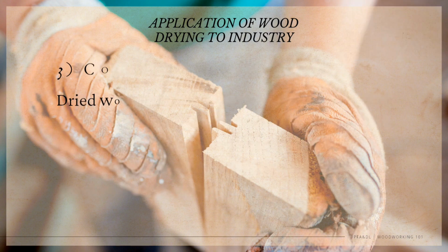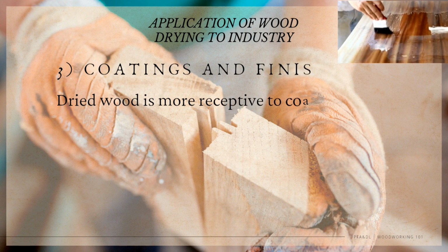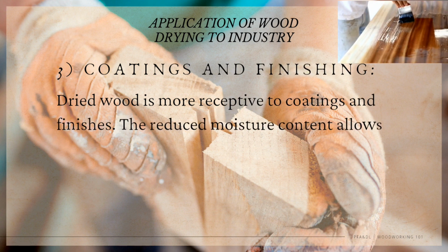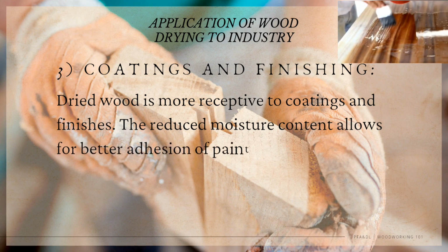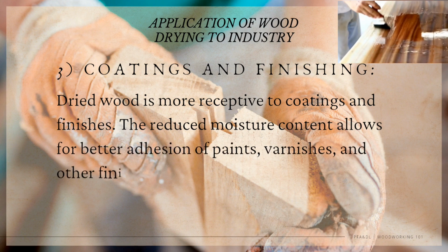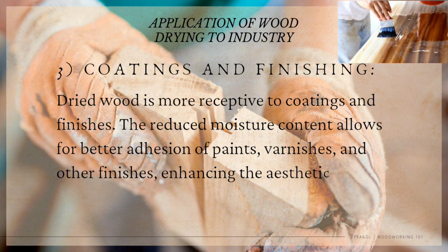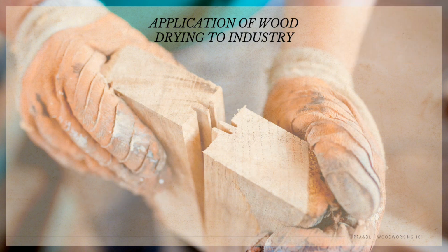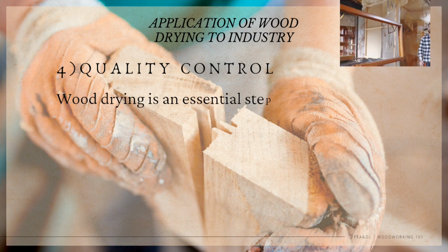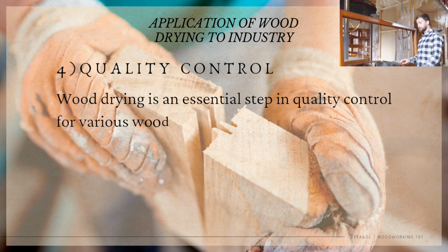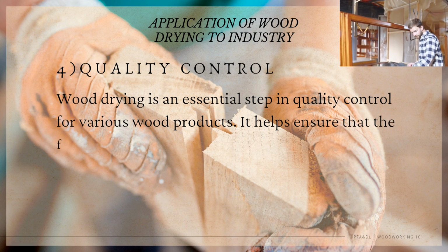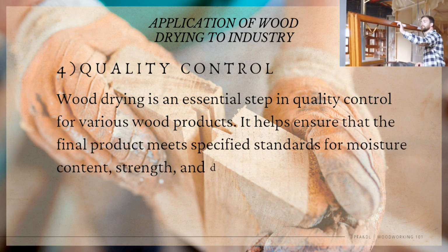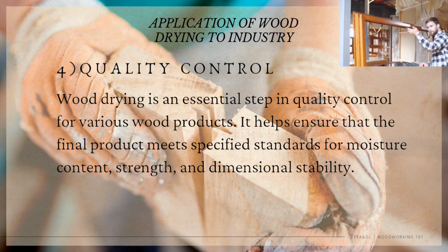And the third, coatings and finishing. Dry wood is more receptive to coatings and finish. The reduced moisture content allows for better adhesion of paints, varnish, and other finishes, enhancing the aesthetic appeal of wood products. And the fourth, quality control. Wood drying is an essential step in quality control for various wood products. It helps ensure that the final product meets specified standards.